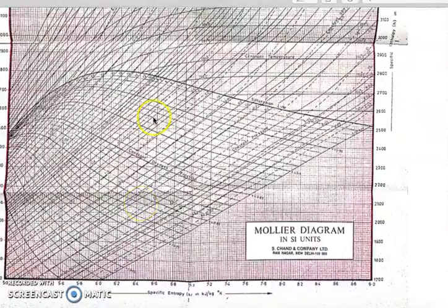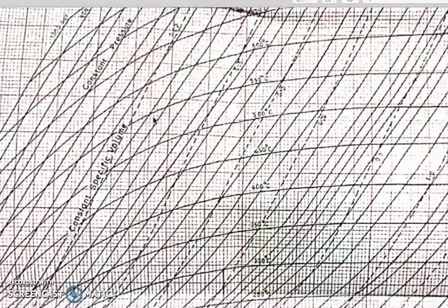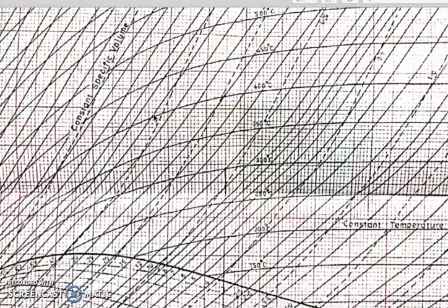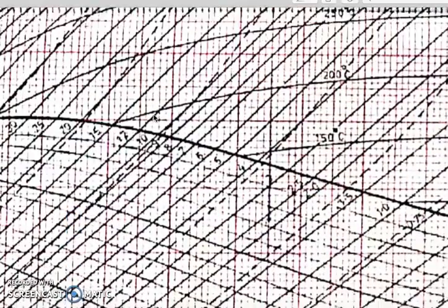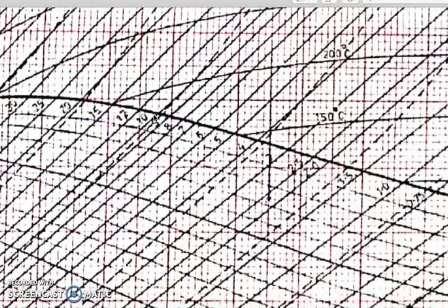Now, these are the parameters. For some of the questions like turbines and nozzles, we will need the condition at inlet only, and then we can find the rest of the conditions. So if I am taking steam at 10 bar and 200 degrees Celsius, let us see whether the condition is superheated, dry or saturated. This is 10 bar and this is 200 degrees Celsius. The two are meeting at this point, and this region is the superheated region.